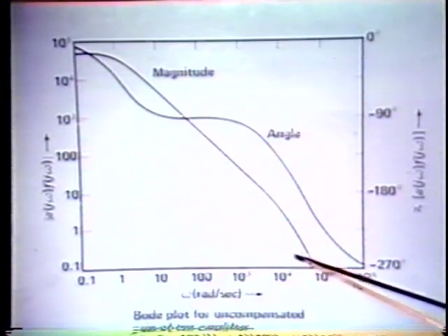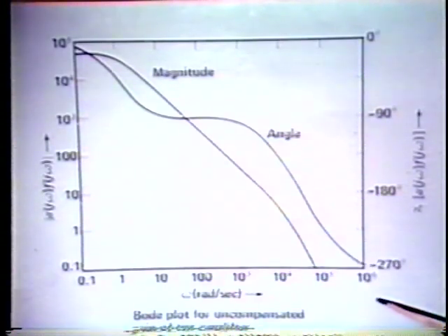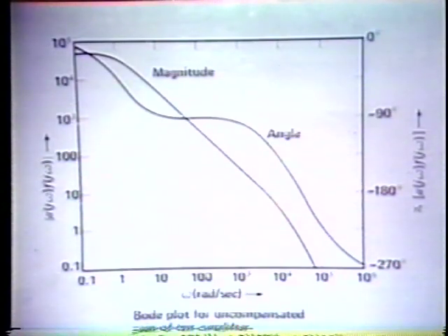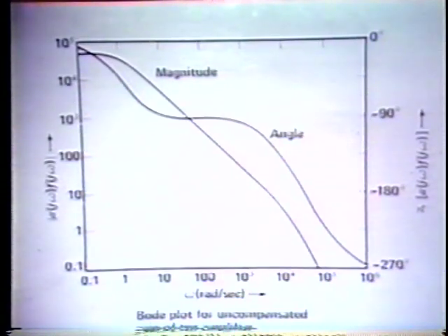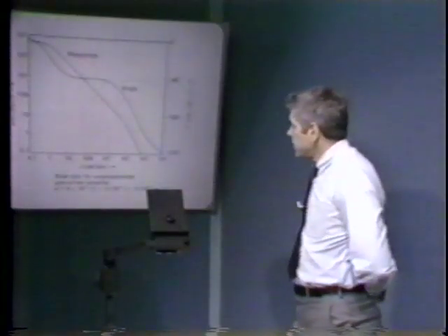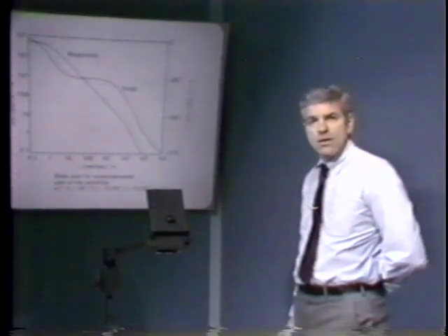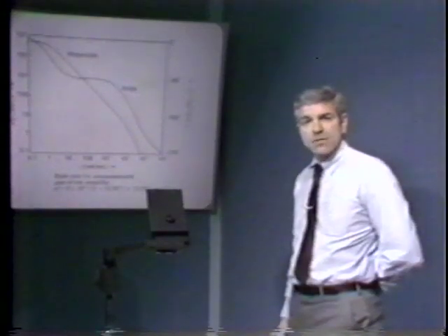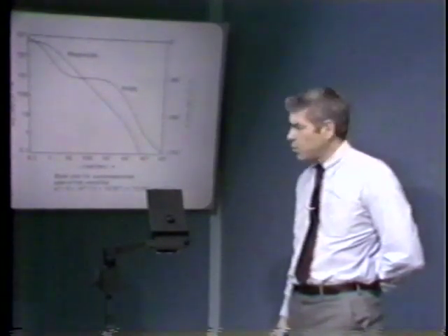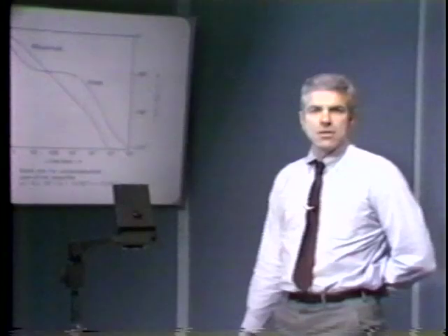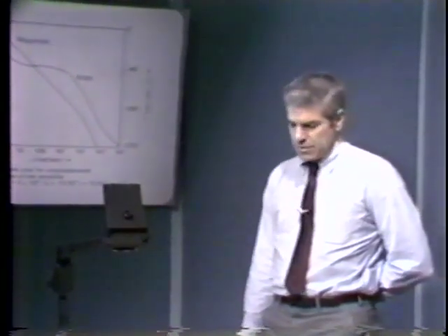If we added a 0 somewhere in here, and of course we get a pole because of the characteristics of the feedback network, a factor of 10 above that, we end up with about the maximum positive phase shift we're able to achieve, and consequently we end up with maximum phase margin for our system. So here we've lived within the constraints. We can build a lead network with an alpha of 10, since that was the attenuation associated with the feedback network. We're able to use that as the maximum spread between the pole and 0 in our lead network. And we live within that constraint, and we choose the best location for the 0 in terms of improving the phase margin of the system.